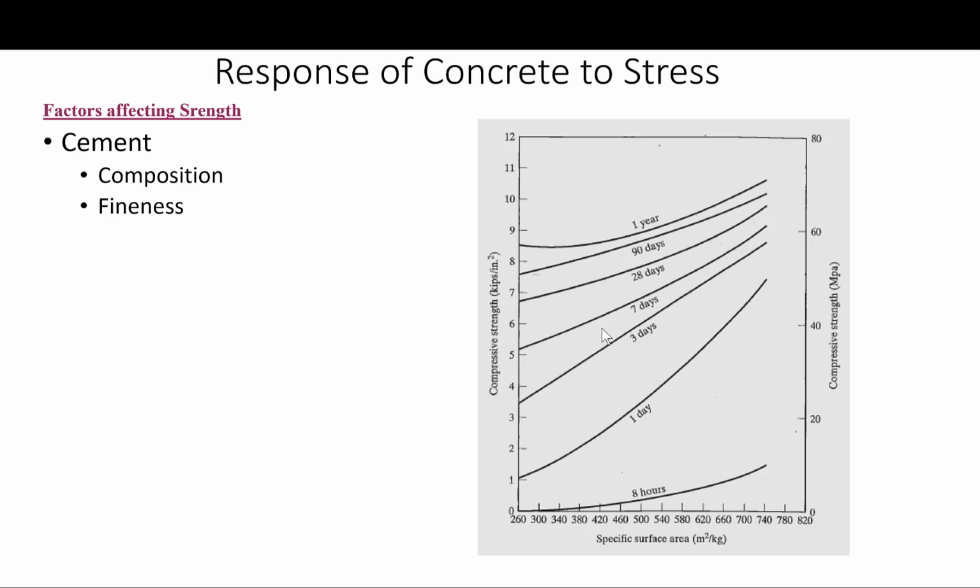But it must be recognized that the variability inherent in cement leads to corresponding variability in concrete strength, and so requires a higher average concrete design strength. Not only do cements that are classified as the same ASTM type vary considerably from plant to plant, but within a given plant, the cement characteristics vary over time.